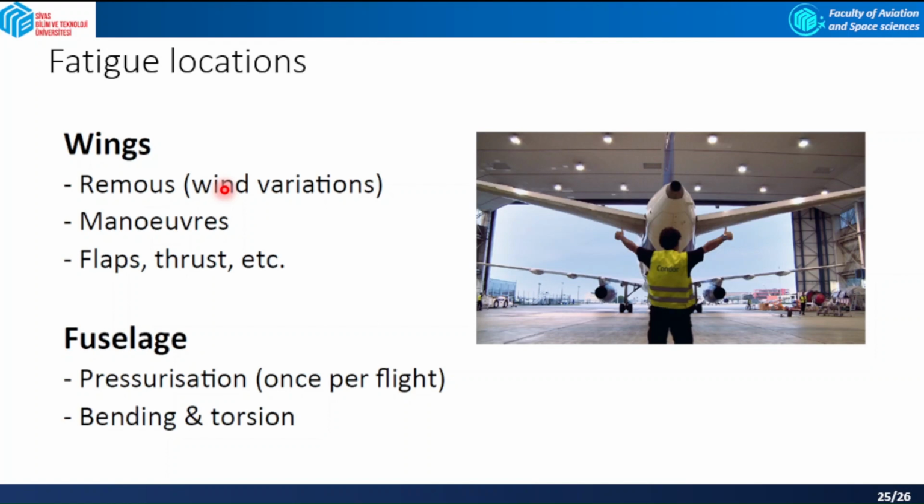And you can have the fuselage pressurization cycle. The cyclic pressurization and depressurization of the fuselage during flight are significant factors contributing to fatigue. The repeated pressurization and depressurization cycles can lead to stress accumulation and fatigue damage in the fuselage structure.